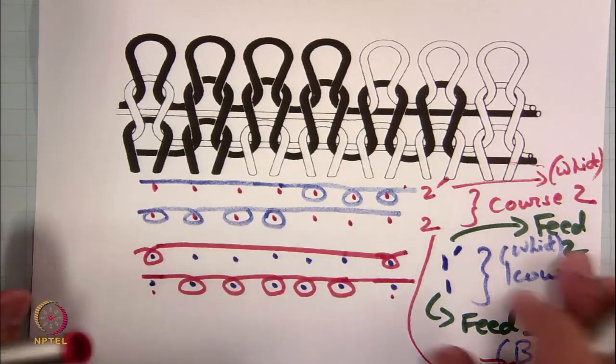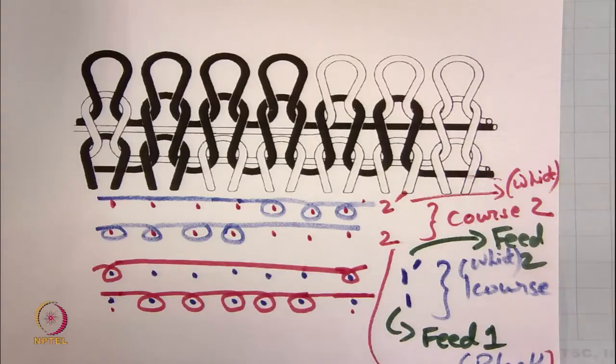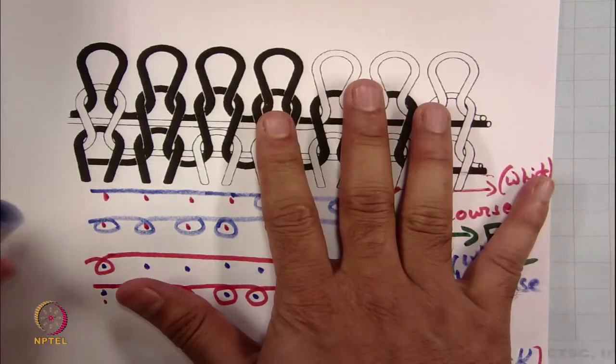So, this is how you create jacquard fabrics, and you can play with the color. Sometimes at some section one particular yarn will be visible, on the other side another color of yarn will be visible. So, this is very useful when you make jacquard designs, and you can decide the colors on the fabric surface depending on the float and the loop. On some side you can make sure the loop is visible, on the other side you can make sure the float is visible. So, this is how you play and hide yarns with these types of designs.